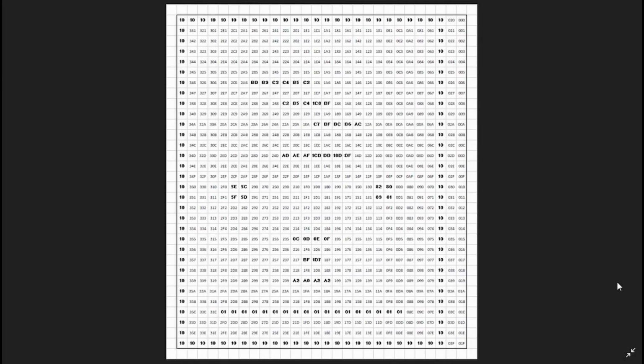So that's it converted to the memory locations. All I've done here is we had our previous memory map, and I've just put in the respective codes for the graphics that we want from the tile set. Next, we need to put that into the actual ROM file and program it onto an EEPROM chip.